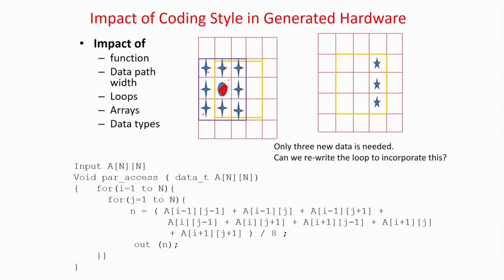If somebody tells you this point, you have to generate this average. Now say that I want to do it in a moving window. First I will do it for this point, then I will do it for this. This is the moving window concept. Again, if I simply give this raw implementation as the input in a high level language like this, your tool will generate hardware to do this. But you see there is a lot of redundant arithmetic involved, right?